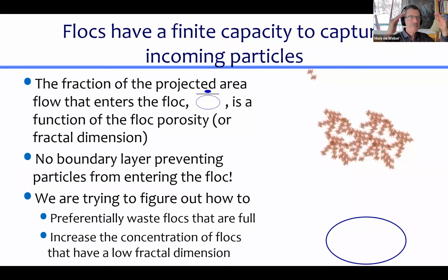Yeah, you're exactly right. Look, the velocity gradient is what's causing the fluid to deform. They're like one and the same thing. The fluid is deforming, and the velocity gradient describes how fast it's deforming. And it's that velocity gradient that's causing anything that's in that velocity gradient to actually spin. So here we have uniform flow up through, and although there is some shear associated with the fact that it's flowing around flocs, there's no big fluid deformation happening. So I'm not going to say that these flocs don't rotate at all, but there's nothing spinning them like there was before.